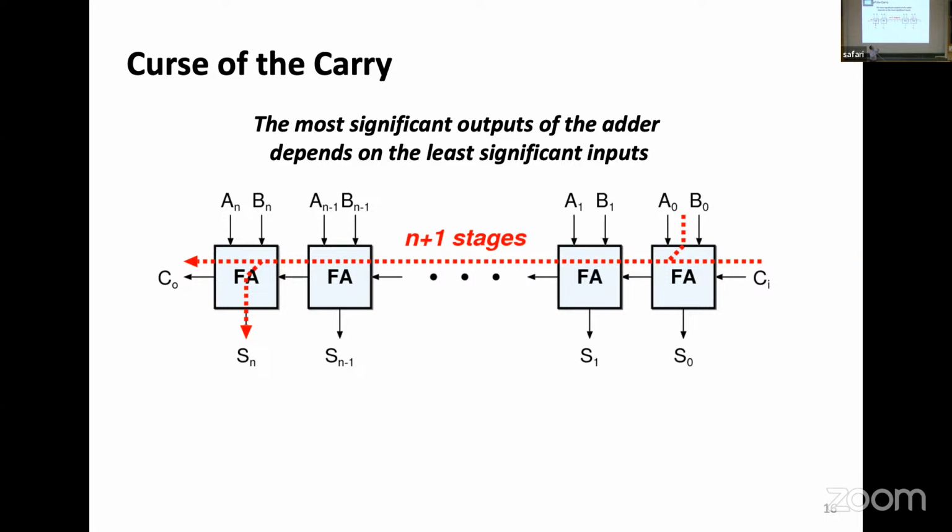You know, A is -1, B is 1, or vice versa. In all 2 to the 24 combinations that I could have written here, which is a lot, these take the longest. There are a lot of additions which can be calculated very fast. It just depends on how much the carry has to be evaluated. And we call these types of adders that have to propagate the carry carry propagate adders, in short, CPA. Now, any questions? This one is important because we will be building on this.